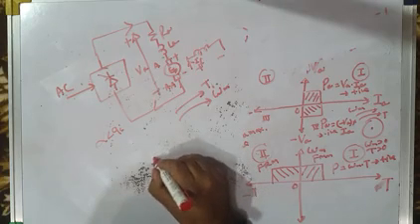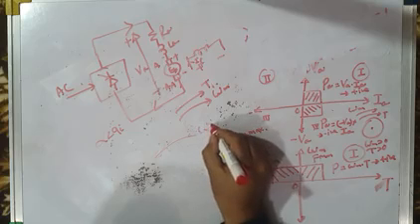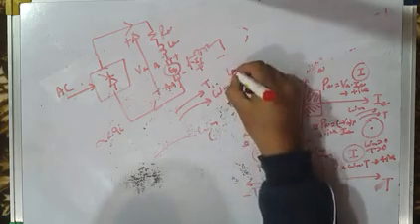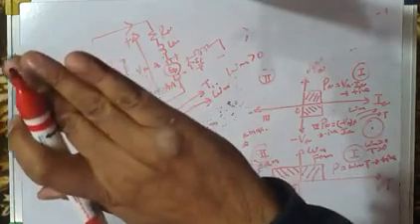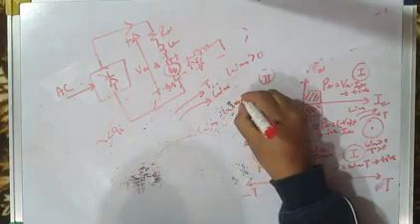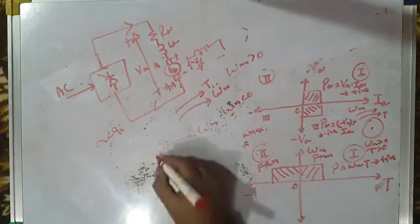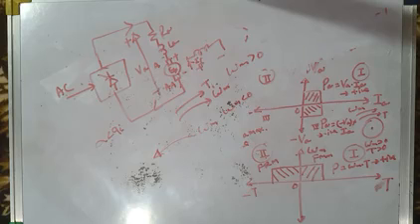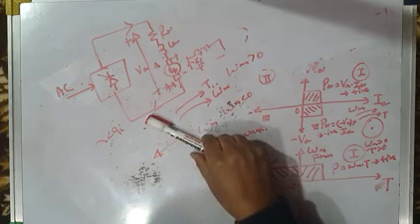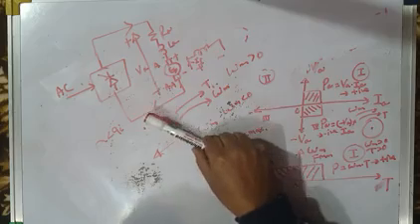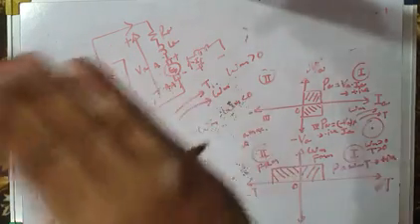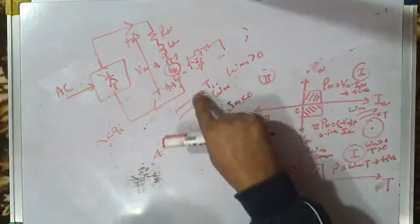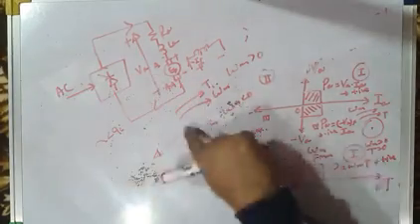So the motor's speed has now reversed, the speed has become negative. Here speed is greater than zero. Now when the cage moves up and when the hoist moves down, speed has become less than zero. Okay, negative speed. Now speed is in this direction. I repeat, when the hoist goes from ground floor to say the 20th or 30th floor, torque is developed by the motor because it has to take the cage up. It is the positive torque. Speed is also positive.